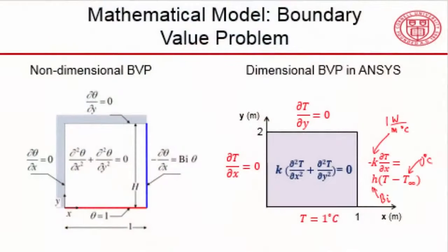Let's complete the definition of the mathematical model. If I go back to a PowerPoint slide from earlier that shows the governing equations and boundary conditions, we can see the entire mathematical model, and ANSYS knows that that's the governing equation we want to solve because we have dragged steady state thermal, and we have set the analysis type to 2D under geometry.